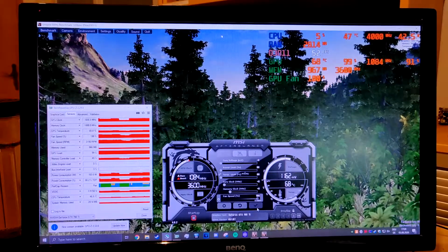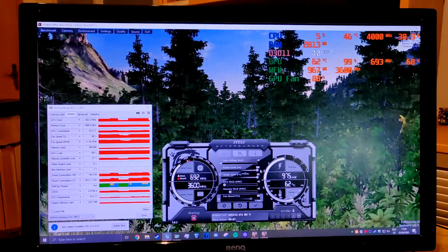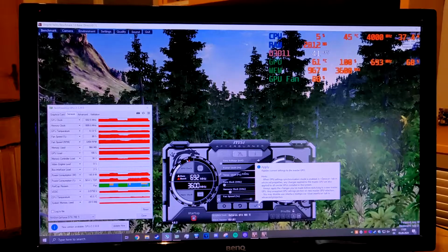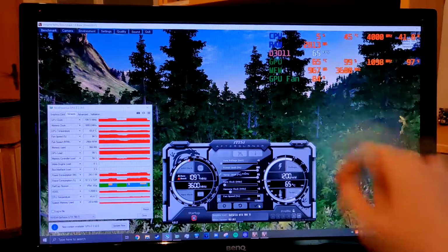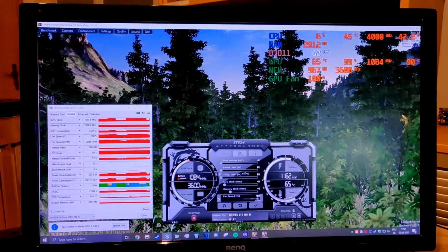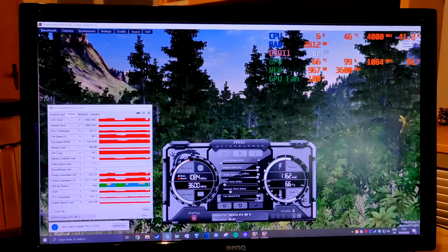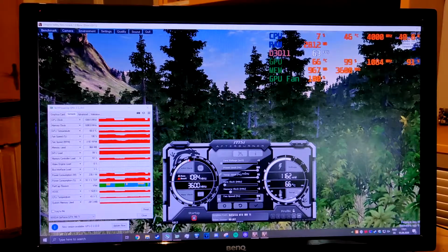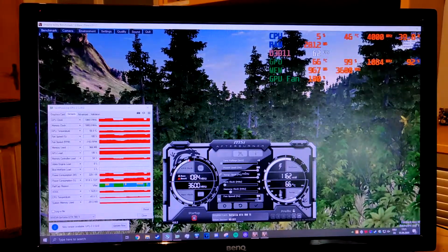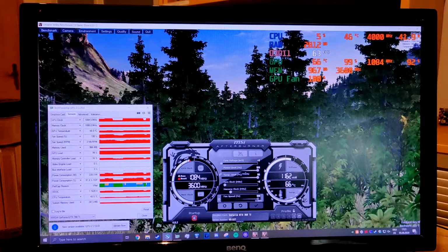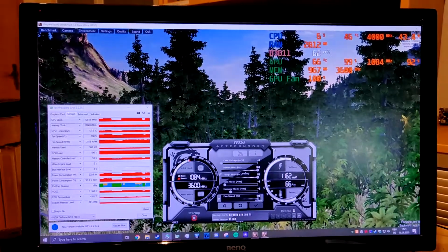The power limit does affect performance. So max that power limit, because you can see 40 FPS, max power limit, 63, 65. That's a pretty extreme example because, well, I dragged it down all the way. But again, this card only has 6 extra percent. Most other cards have around 20% extra if they're not super cheap. And AMD cards can do plus 50% sometimes. So yes, AMD cards are pretty extreme. AMD cards can also still set a static voltage while NVIDIA cards can't.